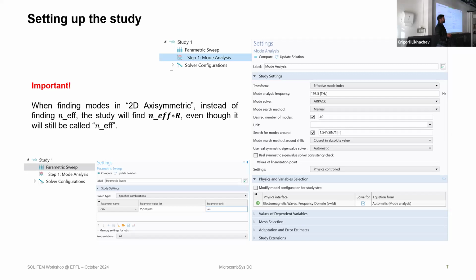Smallest effective area, yes, because other modes are quite big. But then how will you calculate it? That's one way, but I would say a bit tough to estimate. The easier way would be just to calculate the confinement ratio. If you have a waveguide, I'll ask COMSOL to tell me how much of the electric field is inside the core. The largest amount of electric field will tell you that the mode is there. Otherwise it will be 0 or very little.